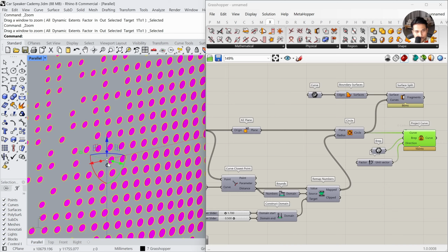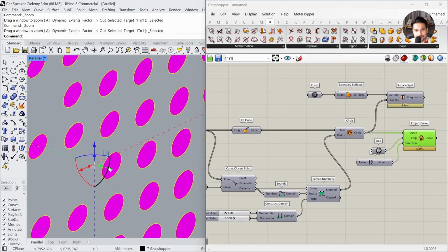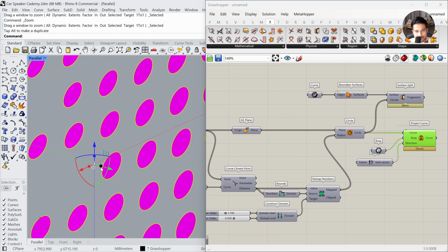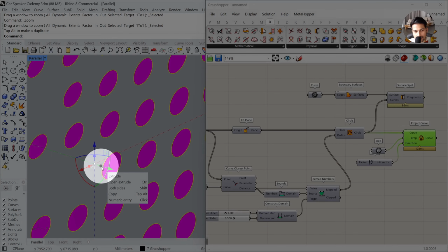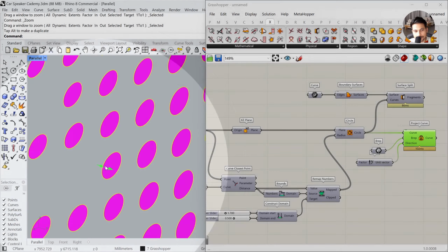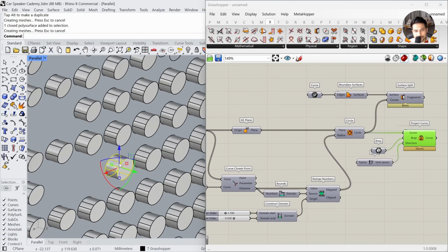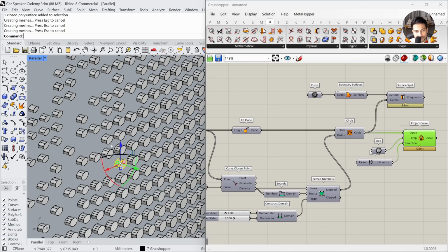Okay, we cannot use these surfaces to make a 3D effect, so we will be extruding it to give it thickness. Okay, so just using the circular handle, we will extrude it by 1.5 units. So let's click there, 1.5, press enter. It's going to take a while. And now we have solid geometries that we can use for perforation.